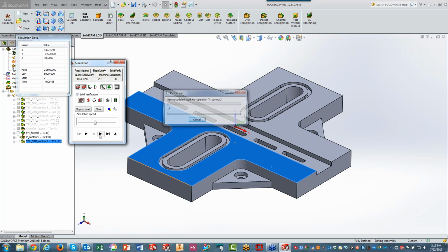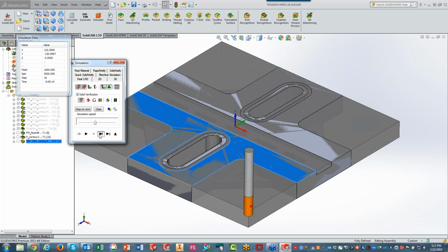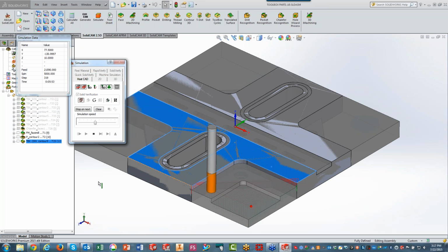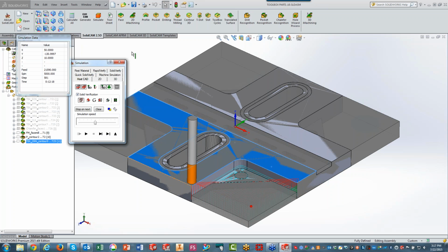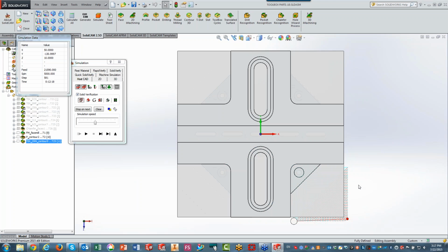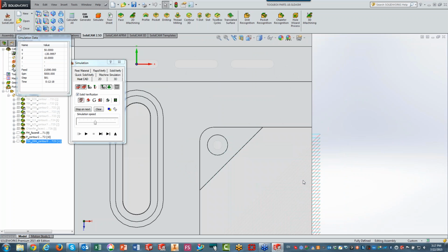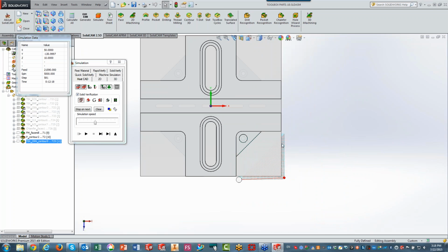And you'll see in this one operation, it's doing exactly what I did before in that one operation. But this time, I had a lot less to deal with. I didn't have to say what my clear offset was to start figuring everything out. I didn't have to deal with what my lead in and lead out was. Everything was done in one simple operation going across. Now, note it went down exactly to its step. And it's also cutting very efficiently. If I take the top look, you see it's only cutting in the areas where there's material to be taken off, in this area over here. Not doing any excess cuts on the outside over there.